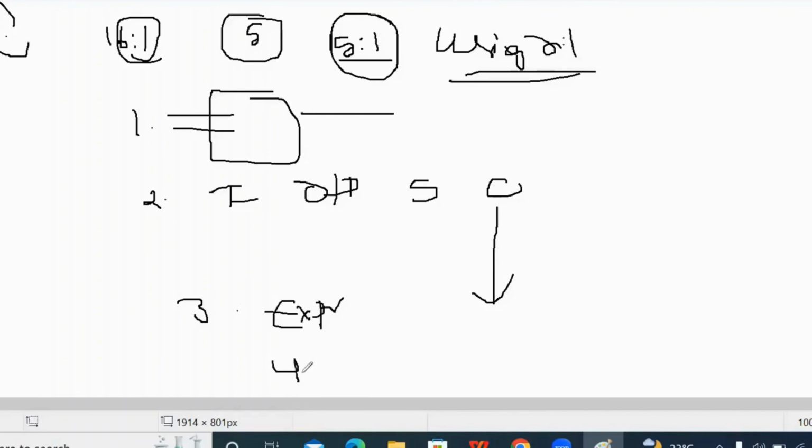Next, what is the fourth step? By using this output expression, you will draw the circuit diagram based on the gates, or if you consider flip-flops. Accordingly, using the expression, you will draw the circuit diagram. From the circuit diagram, you can convert the basic gates into NAND gates or NAND gates to CMOS gates. Based on that, the conversion will happen. Okay, this is how any problem statement will be taken, right? Did you get the point?